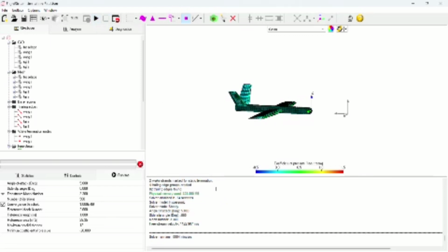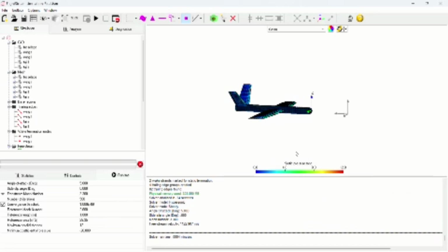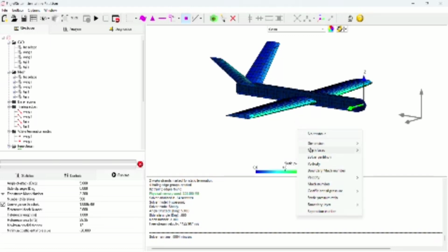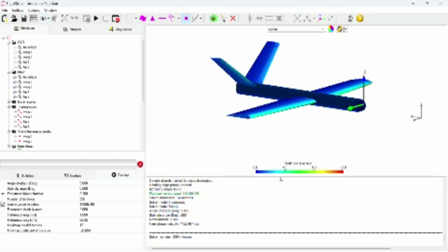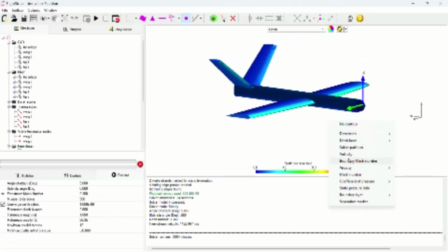So yes, once the simulation is run, we get a coefficient of pressure. As you can see, the coefficient of pressure also varies, and velocity or Mach number, anything, again we can look into whatever static pressure ratio, whatever we want will be available. As you can see, there is a variation in the leading edge and trailing edge. The leading edge has a lesser static pressure, more static pressure, sorry, compared to the trailing edge due to the speed. And anyways, we can also compare the values.